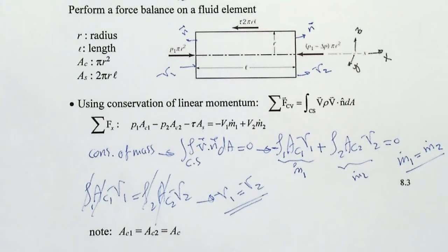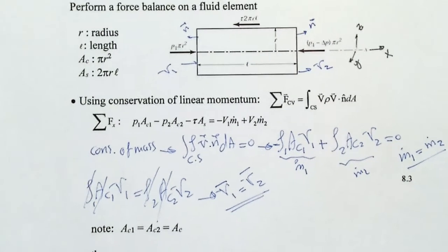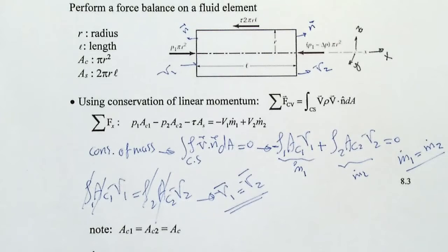But again, that's the velocity profile, right? When you have a velocity profile, it means that for finding the m dot, you cannot apply rho AC V1 or V2 as only velocity, because velocity locally changes over the whole cross-section area. So whatever we are talking about here is the V bar, which means the average velocity, okay?